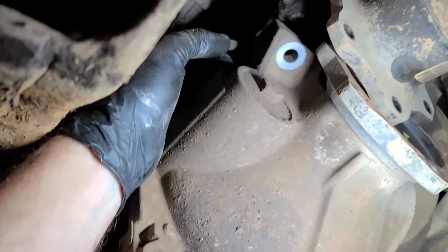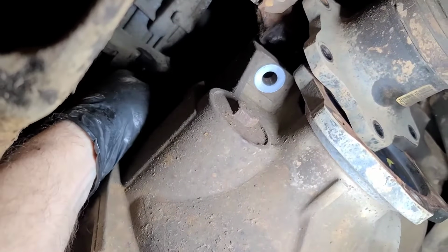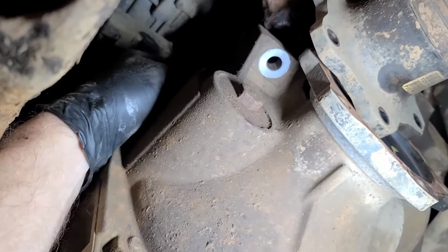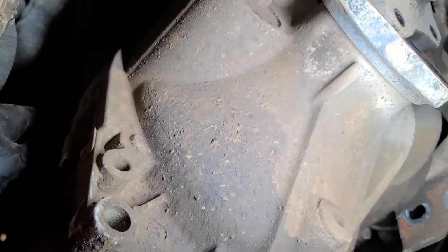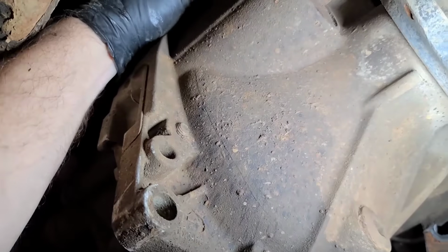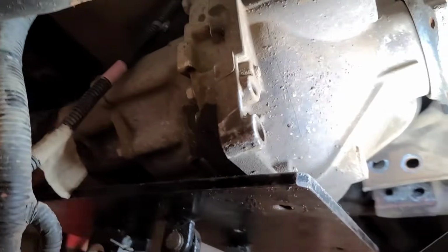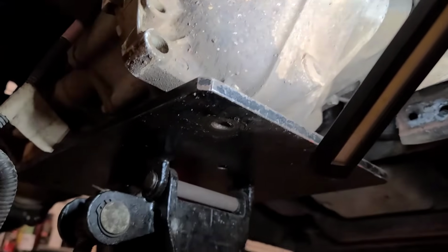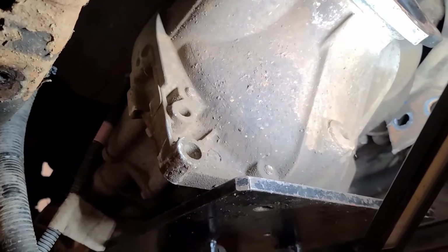So as you're dropping the front diff, disconnect the vent hose up here. It slides off. There are 3 plastic clips that hold the harness that goes to the disconnect motor. They're likely going to break, so you're going to have to tie wrap it in place afterwards. But it's easier to get them after you drop it down about 2 inches. I'd highly recommend a jack to do this. It's not that heavy, but heavy enough that you don't want it falling and ripping the harness connections apart.